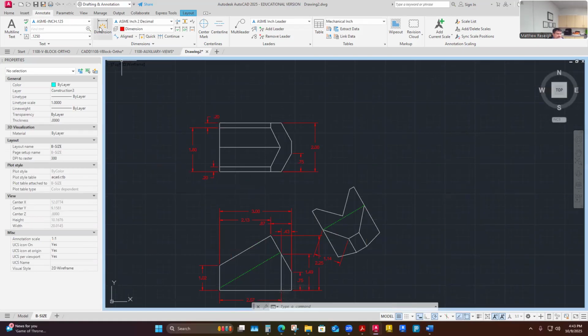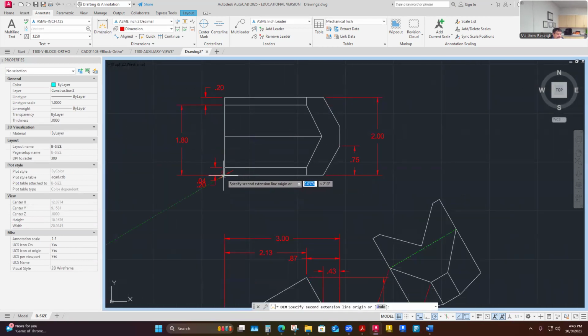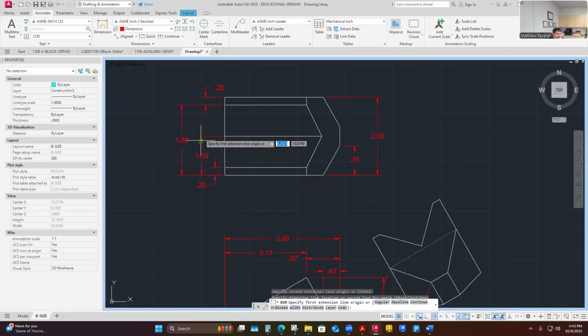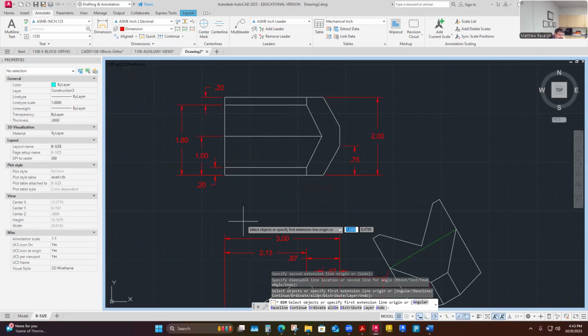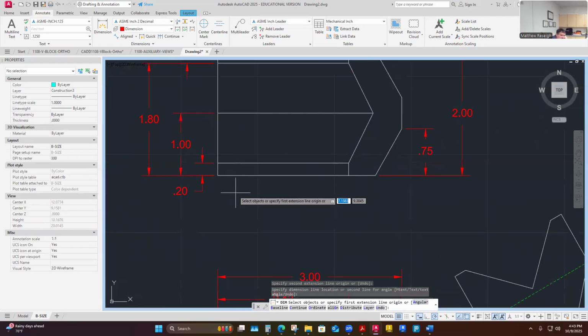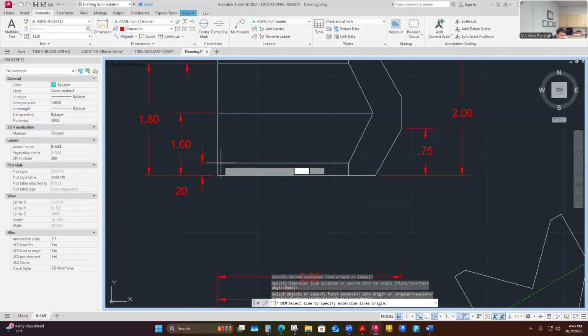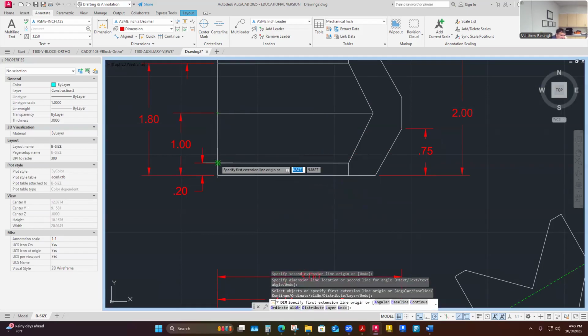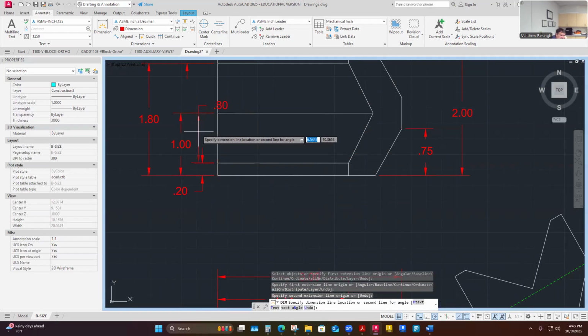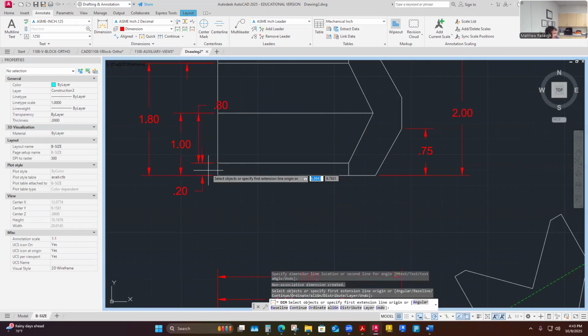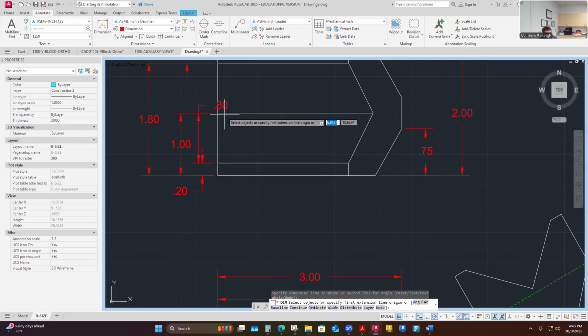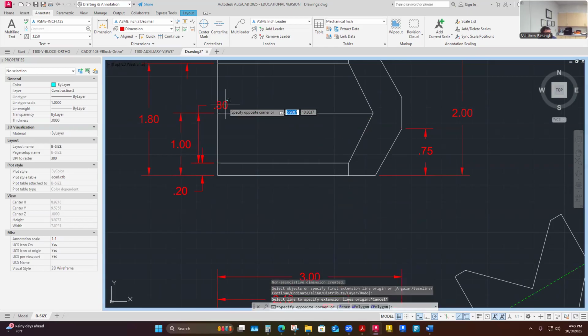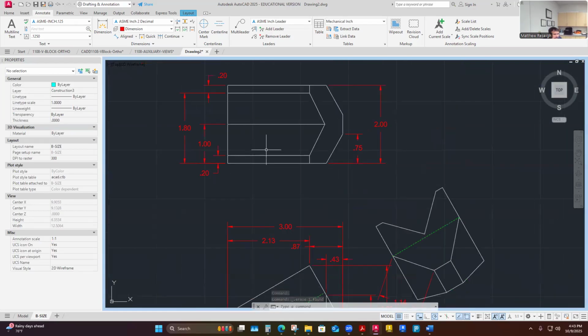Well, I can definitely pick up this dimension from front to center of those. That one is kind of a no-brainer that I like. I'm not picking it up from here to here. I'm definitely leaving some people some math. I mean, this gets pretty redundant if I start doing this. The argument could be made that I could throw that on there and it's a reference dimension. It's a foreshortened dimension though, for one, and that's not the best. That 0.8 is foreshortened. So let me think of what else is in real.